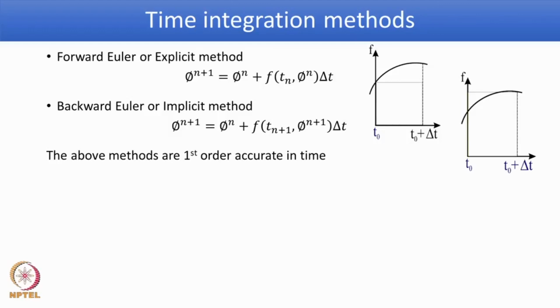If you solve the Navier-Stokes equation in full, we already learned the convection term, diffusion term, and their discretization, and it is possible to increase the order of accuracy for the convection term and diffusion term. It is necessary, as far as possible, for the time integration term also to be of the same order as the spatial derivative terms.